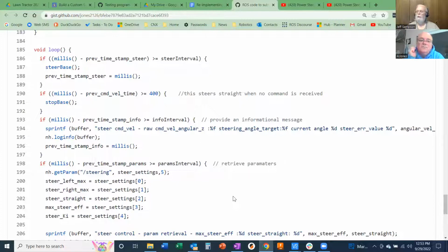And the reason why that's a problem is because if you're writing, say, a word processor or a spreadsheet or something, you're not worried about real-time control. If I say cut and paste this, you don't care how long it takes. You just have to make sure the user doesn't get annoyed because it takes too long. But if you've got something that has to happen every 20 milliseconds, then you have to be careful about putting in something that's going to use more than 20 milliseconds in between those times. So that's why when you start doing real-time control like this, it becomes a little more important what you're doing there. Even though you're putting in print statements, they might come back to bite you, was my point on that.